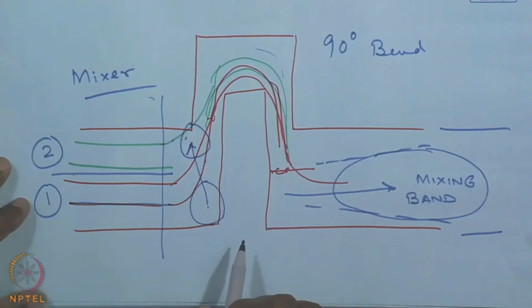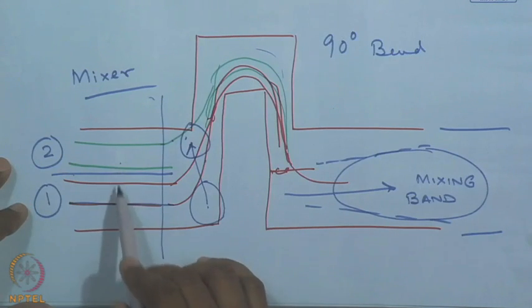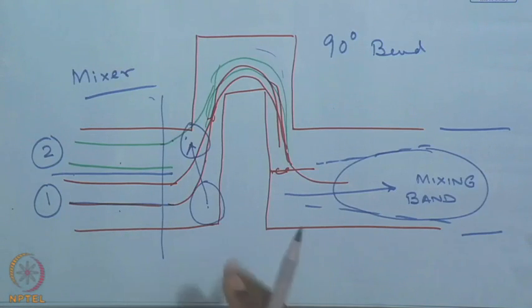That is one of the principal ways to mix two fluids at the microscale, because we know how to mix two fluids in the bulk, but how do we mix two fluids at microscale when they are flowing side by side? When they are flowing side by side in a microchannel, the only way these two fluids can mix is by diffusion, which we know is inherently a very slow process. So in order to speed up the mixing between the two, a bend is purposefully placed in the path so that we get very good mixing.